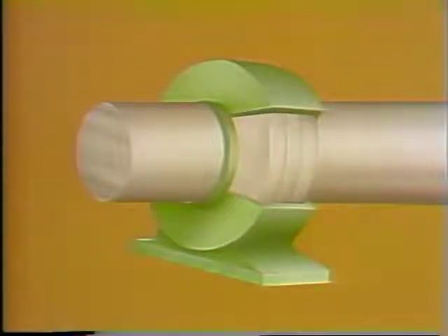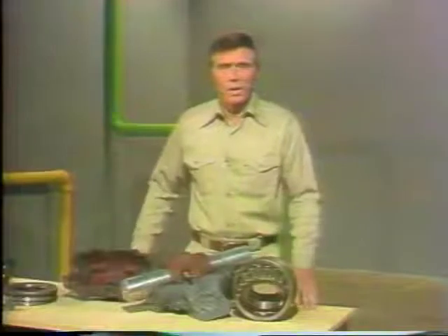Now keep this in mind as we describe how the bearing works. When the shaft tries to move, the rotating ring pushes against the rolling elements, and the rolling elements push against the stationary ring. Since the stationary ring is attached to the housing, axial movement is prevented. This type of bearing prevents axial movement in this direction only. We've now seen how rolling contact bearings and sliding surface bearings perform two of their three basic functions: supporting loads and preventing undesirable movement.